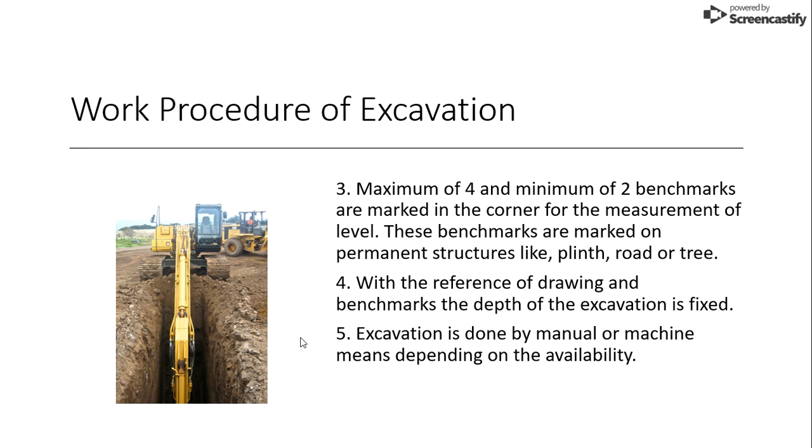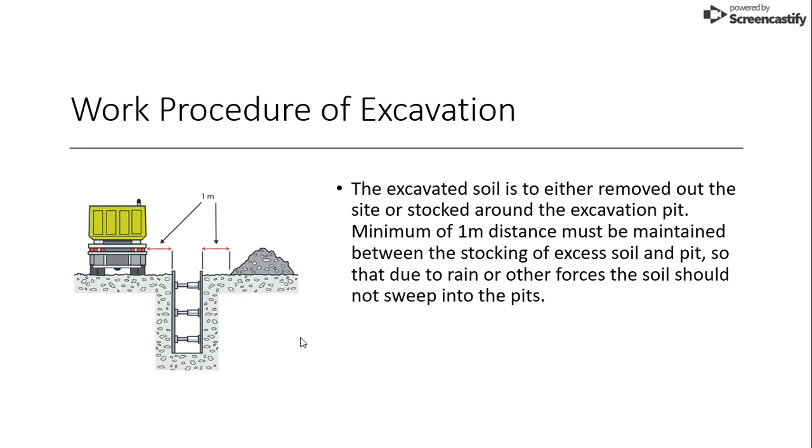With reference to the benchmark level, the depth will be estimated, and the excavation will be done with equipment or manually, depending on availability. The stocked excavated soil will be placed around the excavated pit. There should be a minimum distance of 1 meter, because you don't want the soil to sweep inside the pit because of rain or other forces.